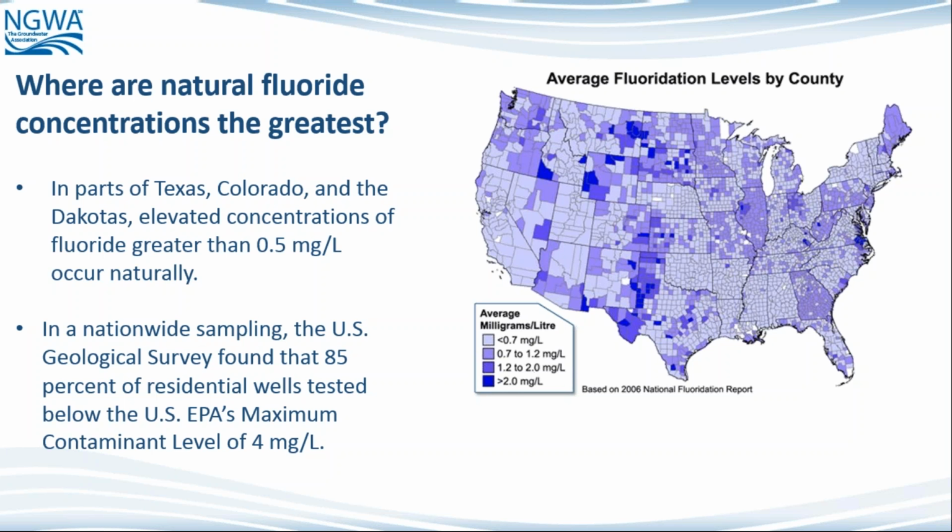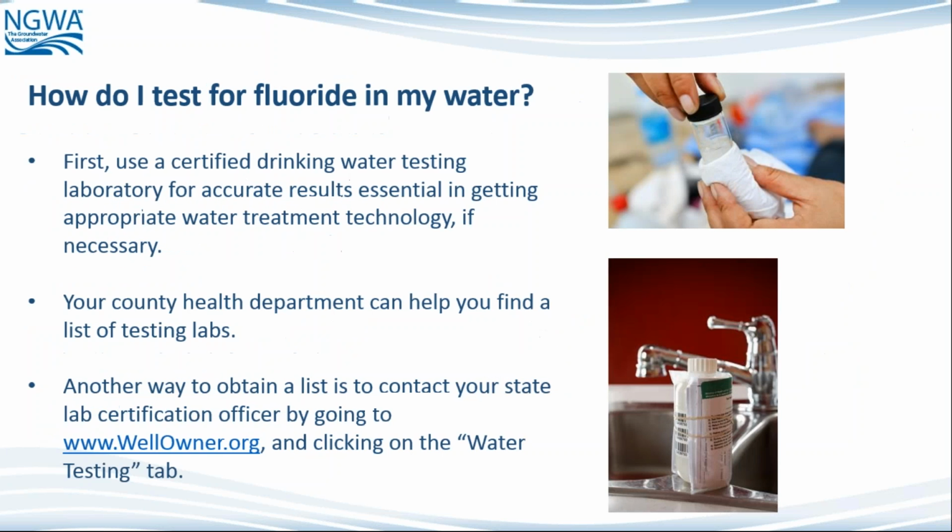But I think anytime we need to at least gauge those concentrations for knowledge that our groundwater system is not above those regulations. So when we look at what we do about fluoride, the first thing is certainly finding out what our source supply situation is. And the first thing would be testing your groundwater system to see where the fluoride concentration is.